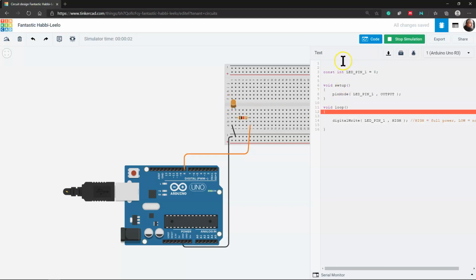So again, when it's coming for the code, the first time it's running the actual program, it's coming down here, making this global variable and a constant, setting it to 8, running the setup function, which then tells the controller to turn on pin 8 for output mode. And then we come into the loop function, and it's continuously writing this line of code again and again. Now, you don't have to have a call again, because it's loop, it's running this, hitting the end, and going back up to the top, so it's running it again and again.